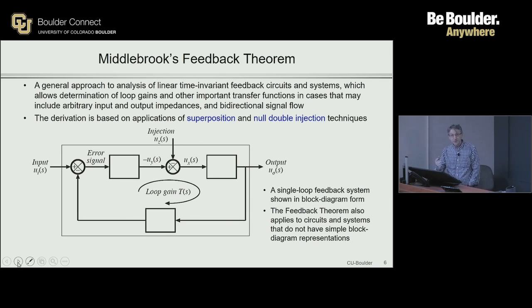It has a name associated with it. The feedback theorem is attributed, and really contributed, by Professor Middlebrook at Caltech. It is a general approach to analyzing feedback circuits and systems as long as they are linear and time invariant. And when we say general, it is a method that is capable of performing that analysis of feedback circuits in cases that do not fall into the standard control theory block diagram form.